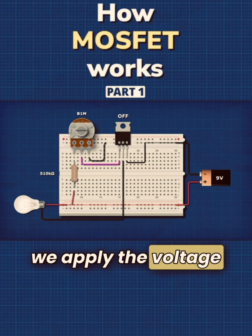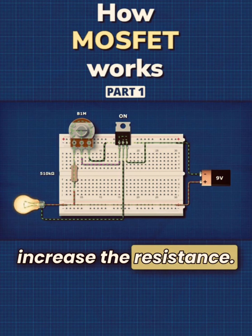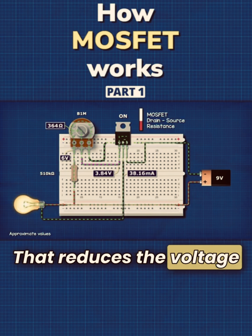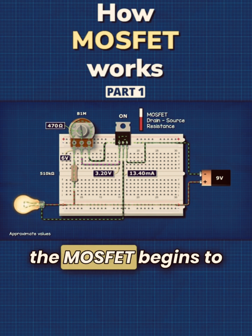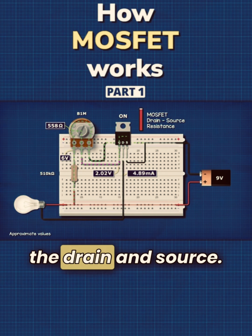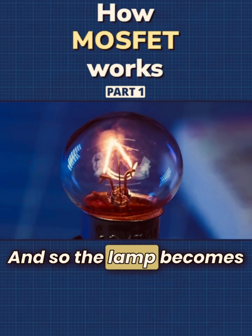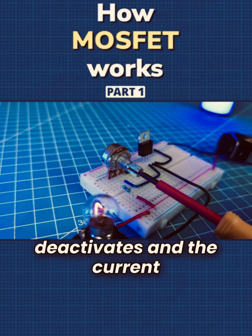If we apply the voltage again, we can rotate the potentiometer to increase the resistance. That reduces the voltage available at the gate. As the gate voltage reduces, the MOSFET begins to deactivate, increasing the resistance between the drain and source. And so the lamp becomes dimmer and dimmer until the MOSFET completely deactivates and the current is blocked.